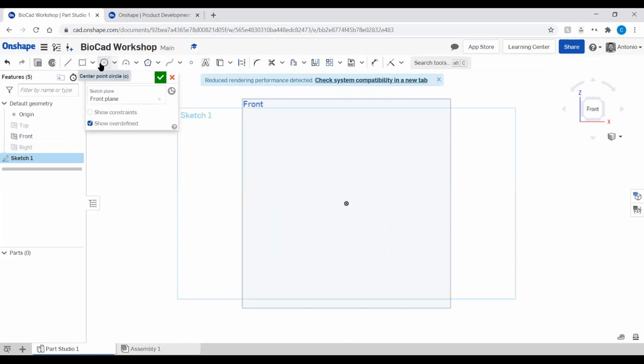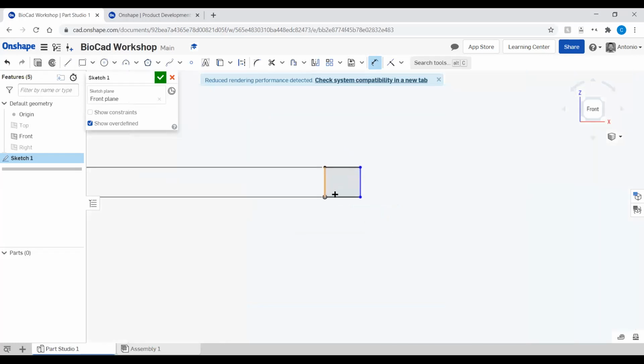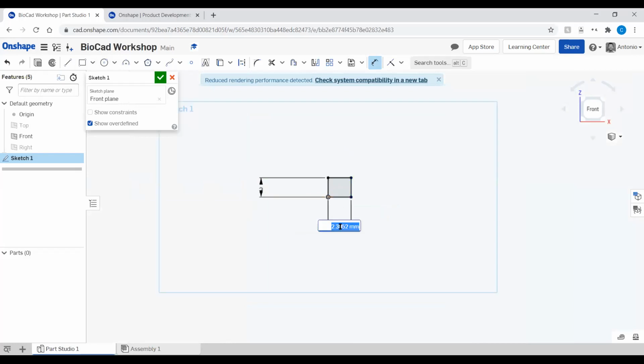And then from there, we're going to set up a boundary for like a quarter of a unit of our mesh cell. So what I'm going to do is click on this rectangle option here and click the center of the origin and just drag this out until some arbitrary feature. I'm going to click the dimension feature here. And I'm just going to make this 2 millimeters big. You can specify 2 mm, or you can just write 2 since we changed our units earlier. You might have to actually zoom in a lot because it assumed that we are working with bigger units, but we're not. We're working with small units.